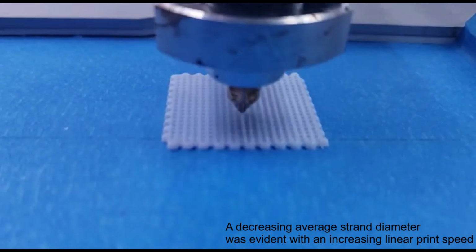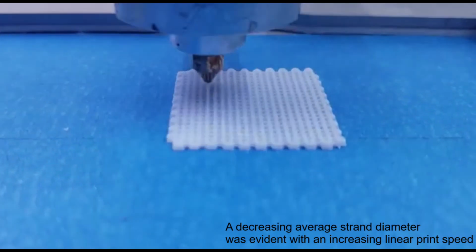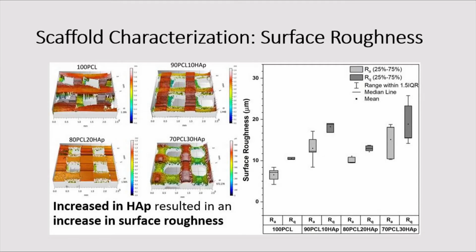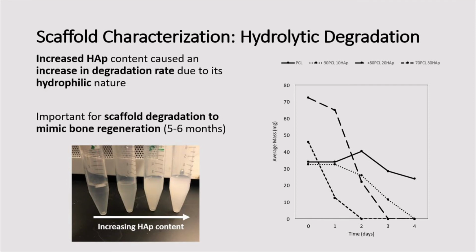The arithmetic average of the absolute roughness and the root mean square roughness were measured for each material composition. Overall, an increase in HAP content showed an increase in surface roughness, which is due to HAP creating increasing local deformities in the material. An increase in HAP content caused a decrease in average contact angle. This is due to an increased scaffold hydrophilicity with the addition of HAP. Hydrophilicity is an important factor for increased cell proliferation.